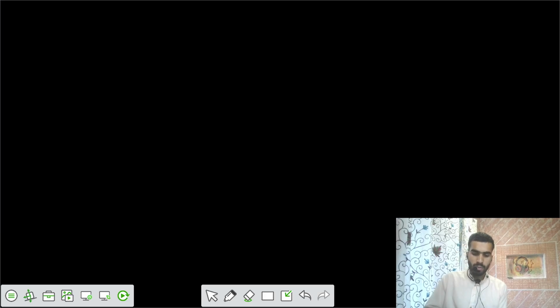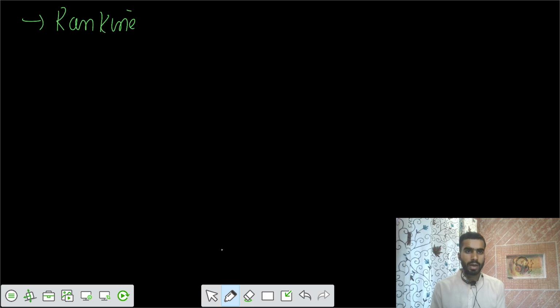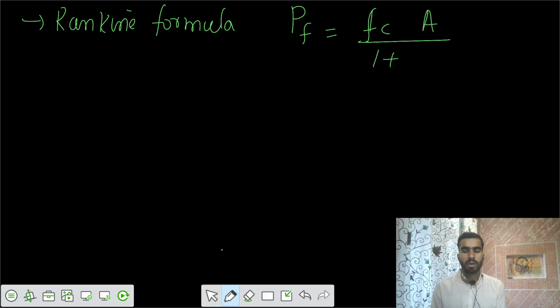Now let's take one more problem. You have to use the Rankine formula. Do you know the Rankine's formula? P failure equals fc A divided by 1 plus alpha lambda square.